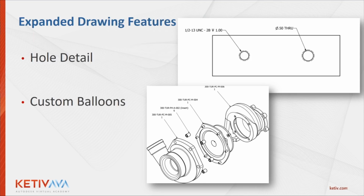Custom balloons. So balloons can be a very powerful tool if you know how to use them. I know when I was in industry, all I really did was use the balloons to number my components, and those numbers related to the items on the parts list. It was great. It certainly served its purpose. But with a little bit of work, we can customize those balloons and get a lot more useful information. So in our example here, we can see that we're using the balloon tool to not only call out the part number of the component right in our drawing view, but also the quantity of that component that's included in the assembly. So we'll look and customize our balloons a bit.